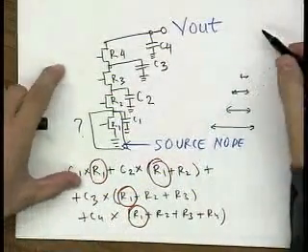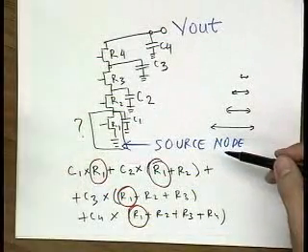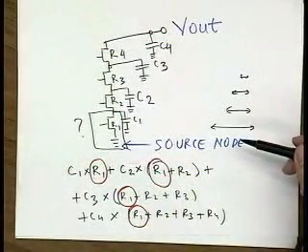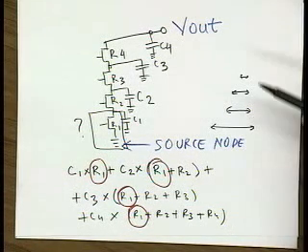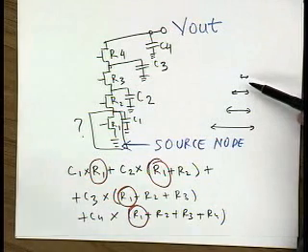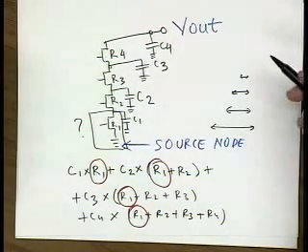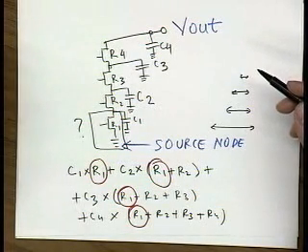So you have a progressive size increase going from the output back to the input. This also works well for the capacitive component, because when you're getting closer to the output, you're reducing the amount of parasitic capacitance, correct? That means you're also making your delay faster. So that works well for both cases.